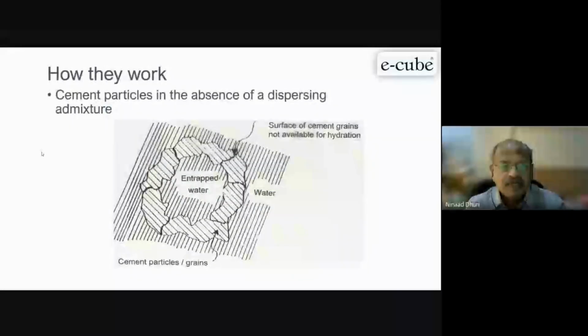How they are working basically. It is basically reacting with the cementitious system, and that is basically giving a temporary effect. So wherever we are having difficulty in getting a workable concrete, workable in the sense when your concrete you have prepared, it has to mix properly, we are able to transport it, then we can place it with manually pumping or any other means which is available at site, depending upon the application.